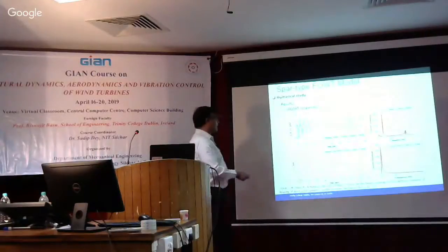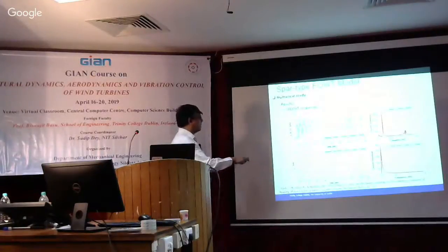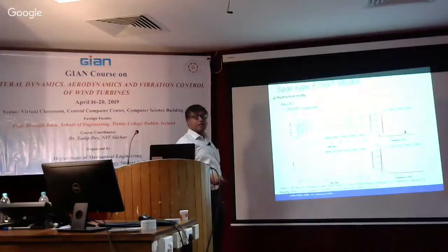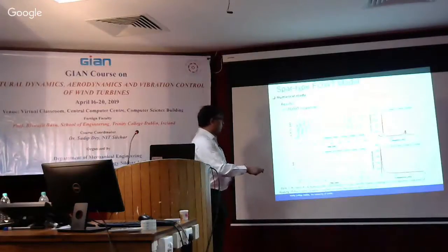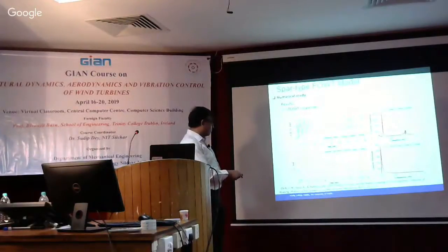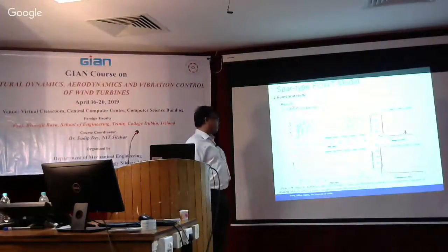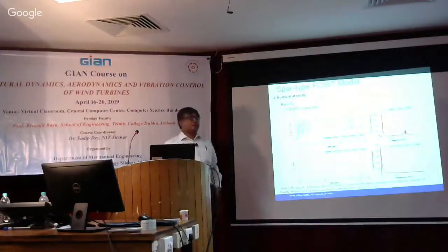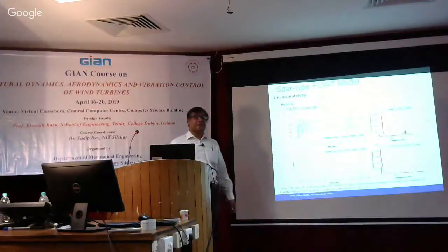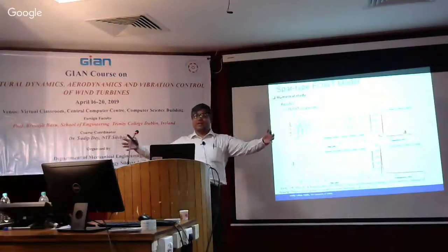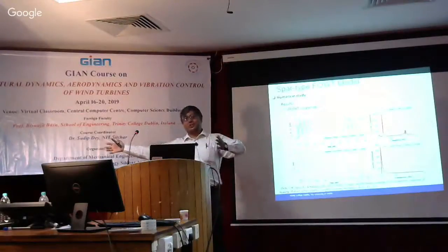This is spar heave. You can see the spar heave is more or less sinusoidal, and it is a long period. You can see the peak is at about 15 seconds here. The next peak is around 45 seconds here. So 30 seconds. You can see that the offshore floating turbine has a very long period motion.